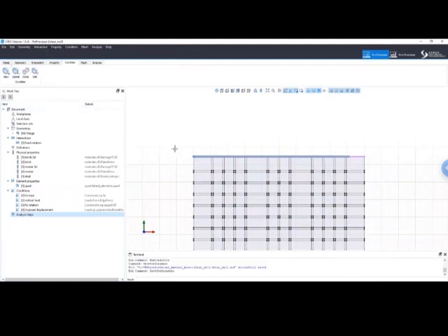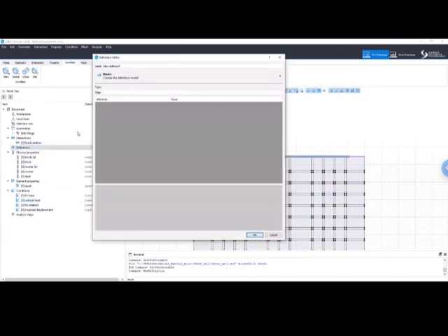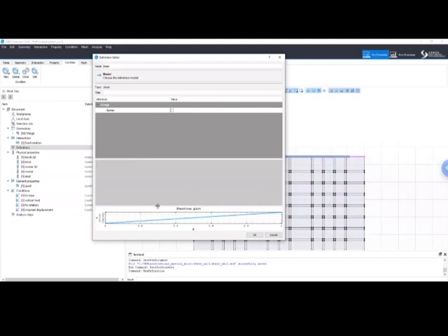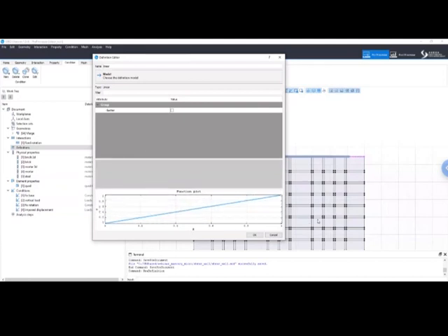And let me create a couple more things. We need to create some time series, okay? Because we will need them to define how the vertical load and the imposed displacement will evolve during the analysis. So the vertical load will be applied in a linear increasing fashion. So we just need a linear ramp. So let's call this one linear. And let's choose a time series which is linear. So this is perfect for now, from 0 to 1.